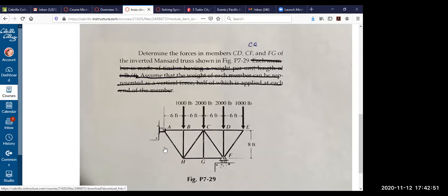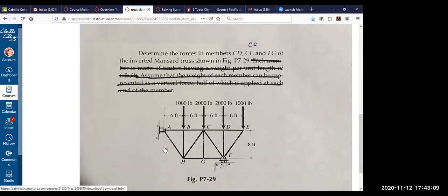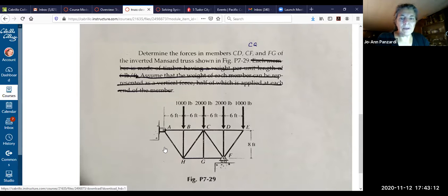Okay, so we solved for AX, we solved for AY, and we solved for FY, and we found all three of them. What's another equation we could do to check it? Because we're going to do an awful lot of work, let's check it at the beginning to make sure. What do you want to do? It's for a check. We could do a moment about a point. Great.